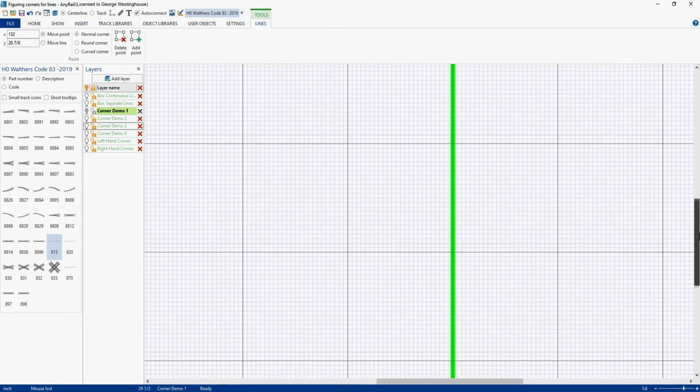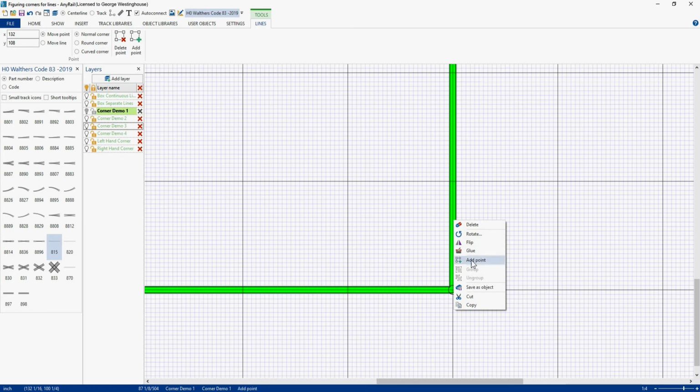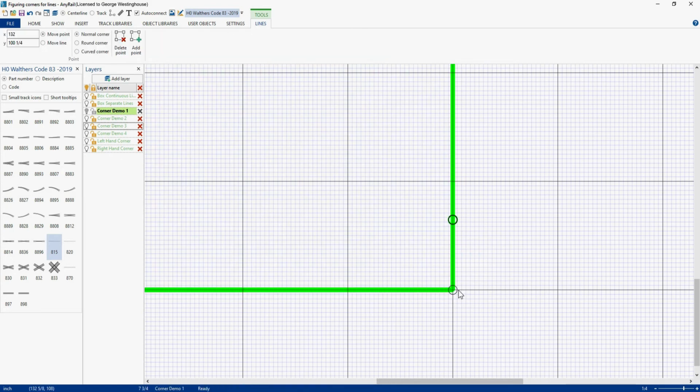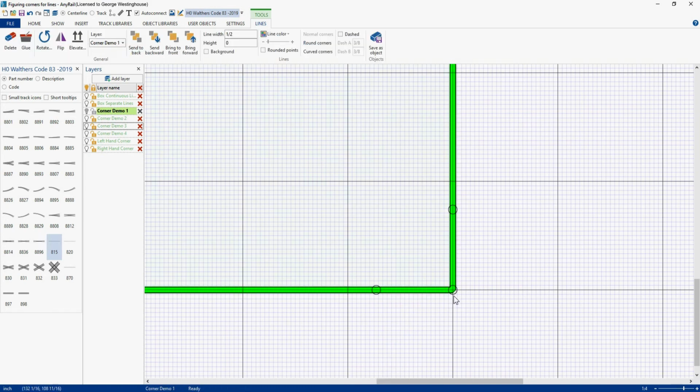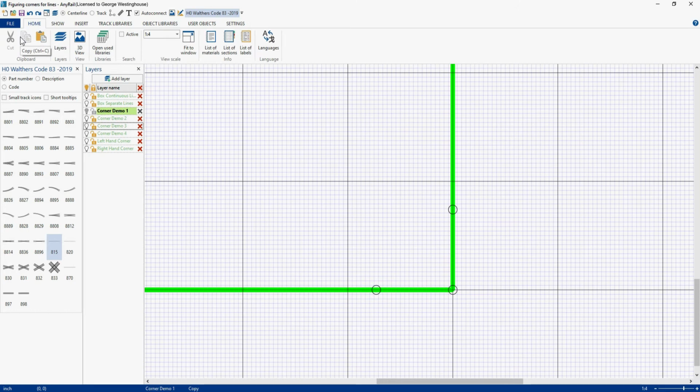And then just to show you, I know, it takes some time. We're going to look at this point. We're at 132 and 108, and I want to put a point up here. I'm going to subtract from 108, and I'm going to come up with 99.125 for my Y. And I'm going to subtract from 132, and I'll end up with 123.125 for my X. Oops, grabbed the wrong point.